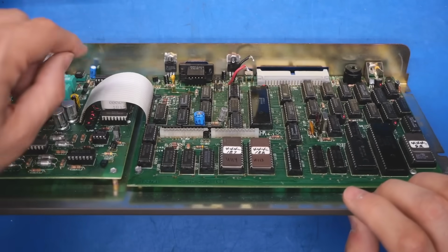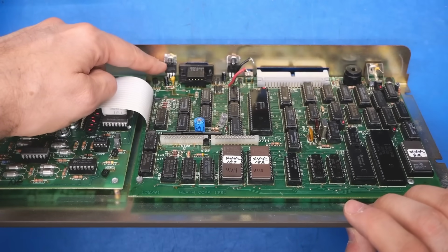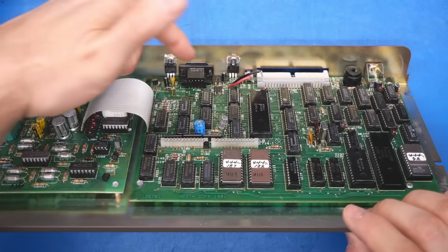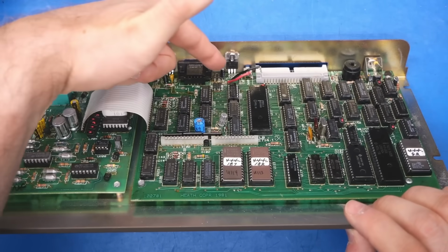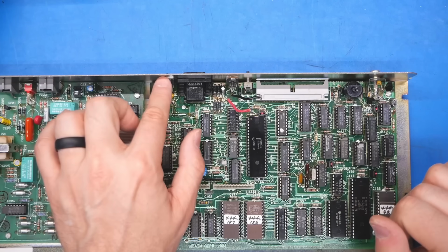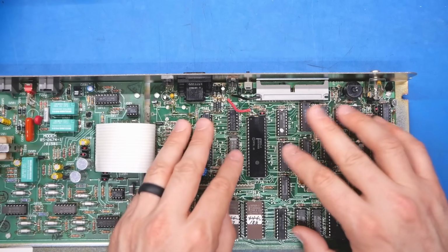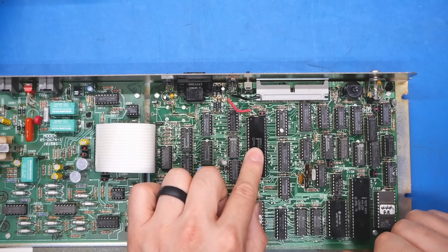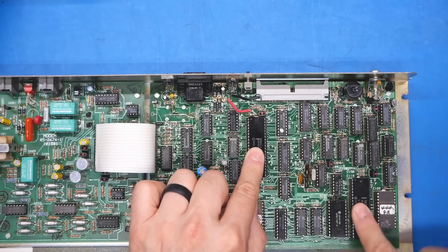Kind of like the fact that this has 2 different voltage regulators, a regular 7805 and some kind of National Semiconductor custom part, which almost certainly is just a 7805 as well. I just don't really get why they're not the same exact part. Why would you have 2 different parts? We know that this voltage regulator supplies the logic to pretty much all the TTL ICs, and this one is supplying the voltage to the main microcontroller and the video controller.